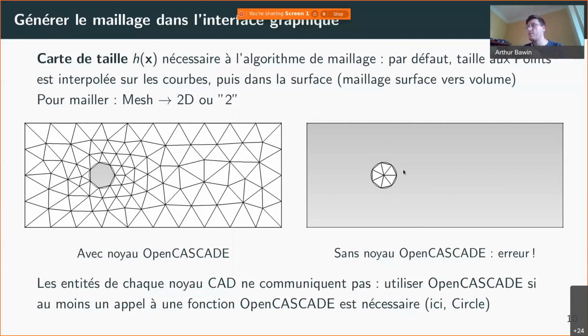So it will try to do the best it can with different identifications, each starting at 1, and it's a mess, and it's going to mesh the surface you don't want to mesh. It's essentially going to create a surface that is bounded by this loop of lines instead of this one. So this is not what you want to do, of course.